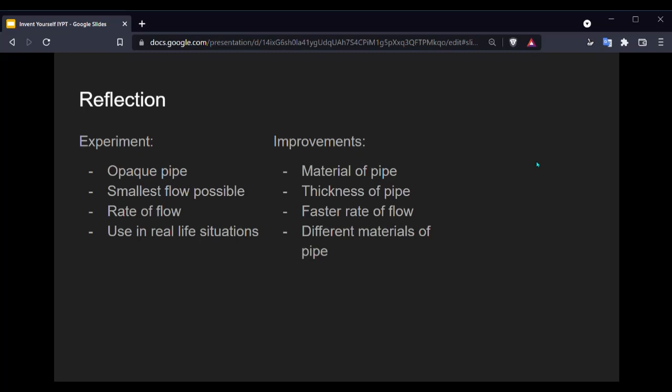Another aspect to consider is a larger diameter pipe or thicker walls of the pipe. More energy would be required for this method to be effective, and more sensitive temperature gauges. Perhaps insulated temperature gauges would increase the performance, as external factors would not be affecting the reading as much.